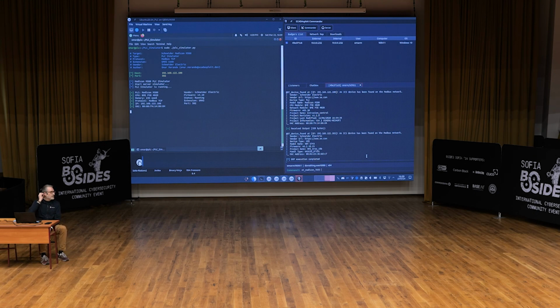When you program a PLC, you consider a PLC as a PC. It means that if you are familiar with the development tool, you have a debugger inside your Visual Studio Code. You can put a breakpoint to stop the execution of your code, and then step by step analyze the data, changing the data, and so on. You can do the same with a PLC, using Unity Pro for Schneider or TIA Portal from Siemens.